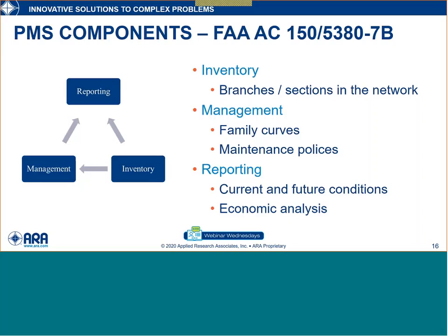And then reporting, getting out the current PCI value, the predicted future PCI value, when it's going to fall below that critical PCI where we need to program rehabilitation, things like budget analysis, unlimited, constrained budget, backlog elimination budgets, various economic analyses like that.